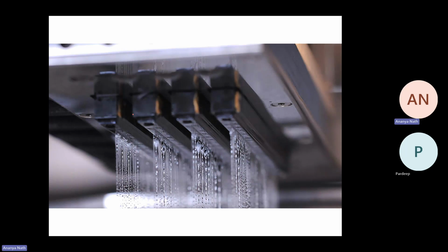Then this was the photo from the last process. Actually, it came here. This is the binder jetting nozzle from which these binders are coming. Binders means the glue for the binder jetting. The process where we put the powder on the build plate and then the binder was coming. So this is the photo of the head from which the binder or the liquid is coming, and this is how it looks like. This is how the glue comes, spread or put over the build plate full of powder particles.